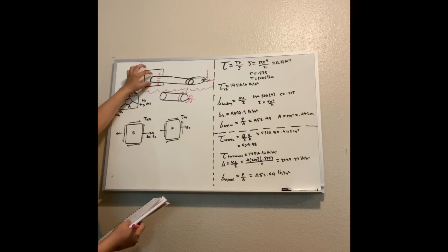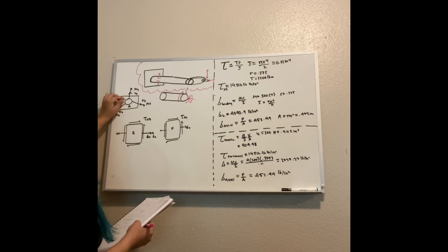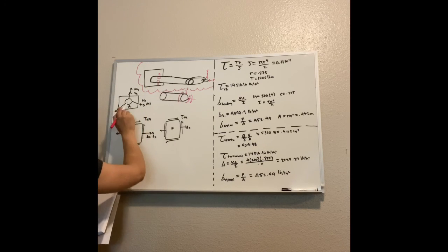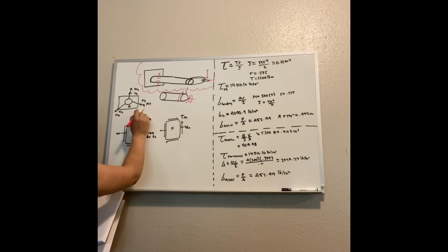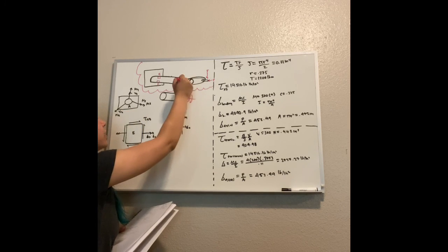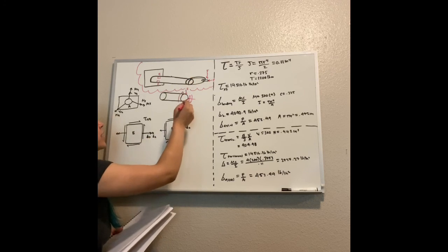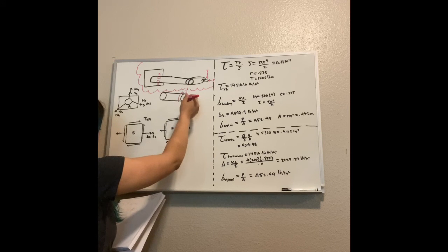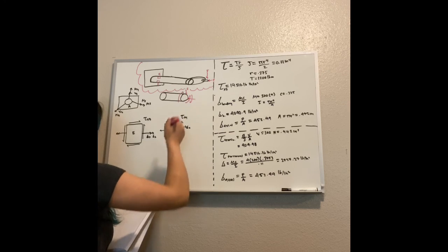If we zoom in right here and look at element A, which is just the beginning part, we see that in the y direction there's a shear force, and also a moment. We also have in the x direction a normal force and a moment, and in the z direction a shear and a moment. If we zoom in to this part of the component, we have the force coming down, a torsional force, a bending force in the y, a bending in the x, and an axial force.